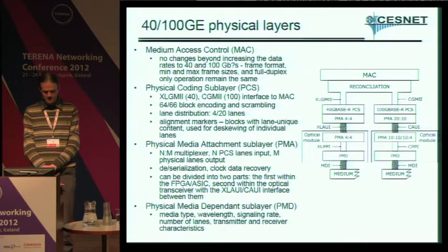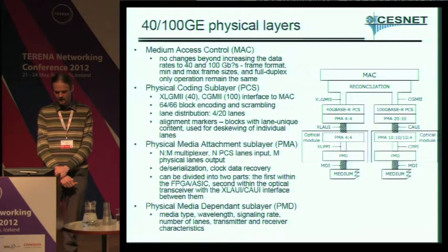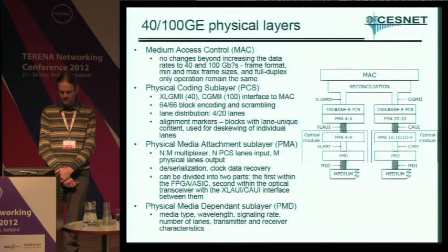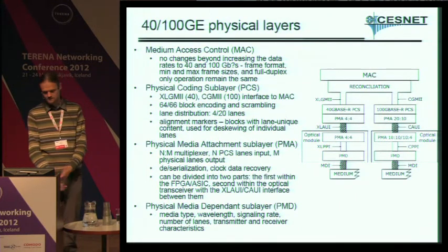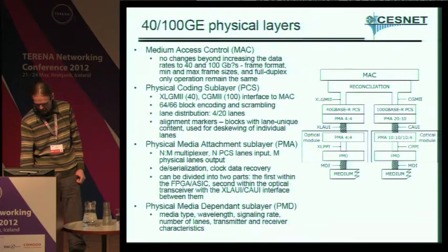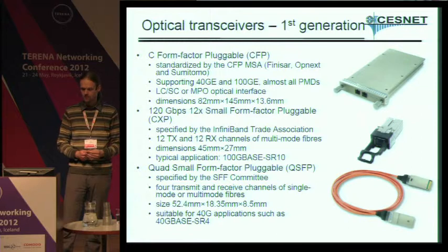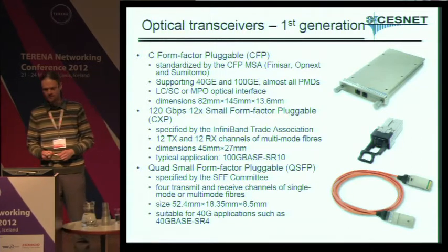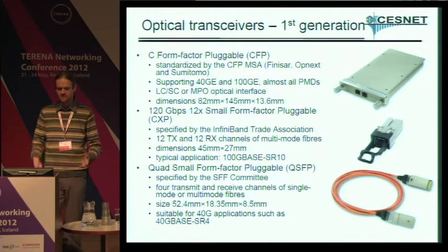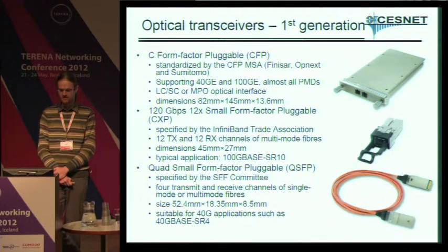The PMD physical media dependent sublayer is just the conversion to the optics, so it's nothing really new in here. The optical transceivers, how they look, well, they are new, of course, but not in principle. The golden standard for this is the CFP, which is standardized by the most big players in this. And the advantage of these transceivers is that they are almost universal.